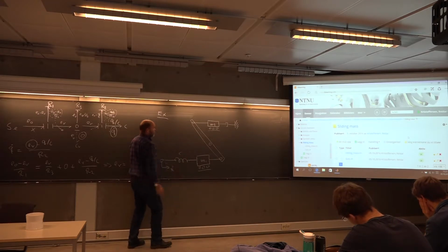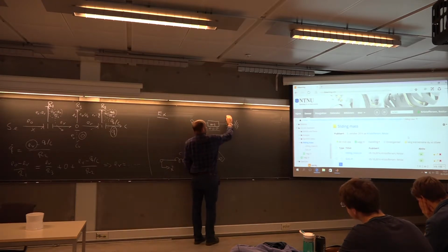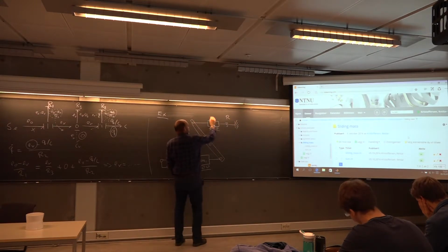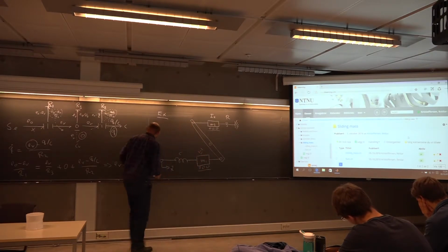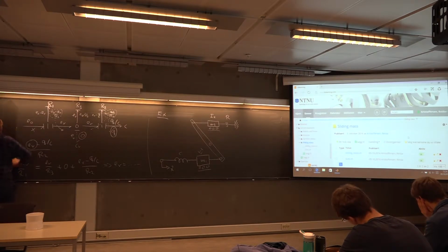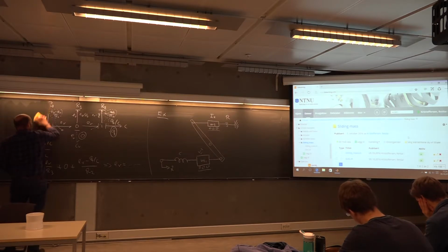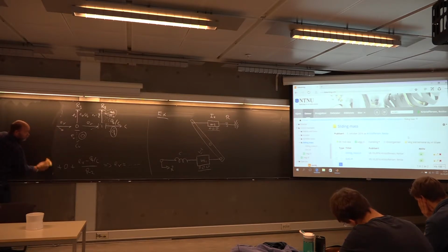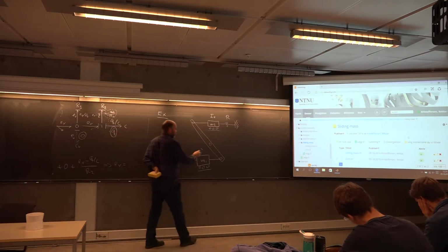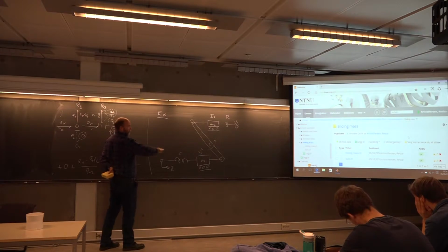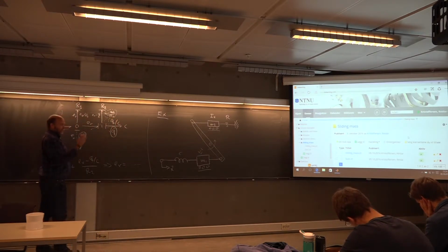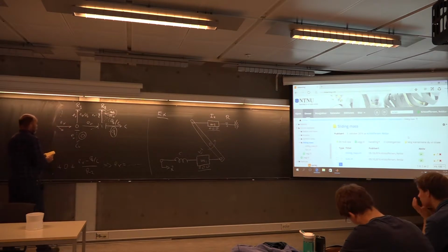Here I have a spring C, I have a damper, an R element, inertance 2, inertance 1. So how to solve that one? Well, this long stiff arm is then of course going to rotate around this point. But I treat the motion for the two masses as linear. So if the angle is not too large, then that should be okay.